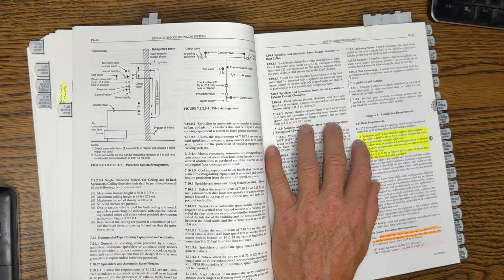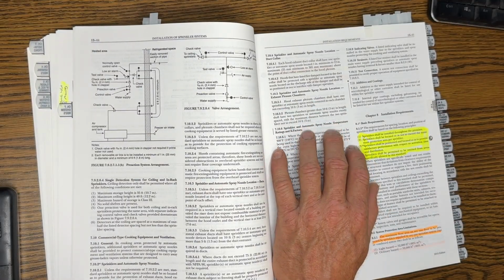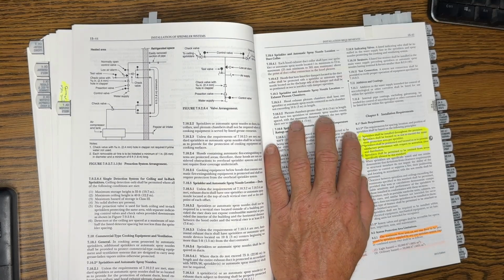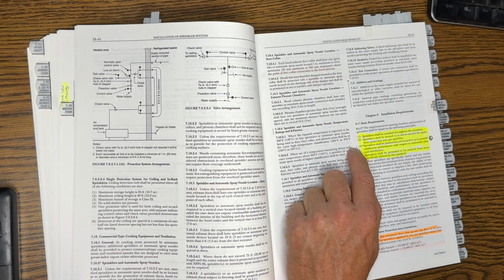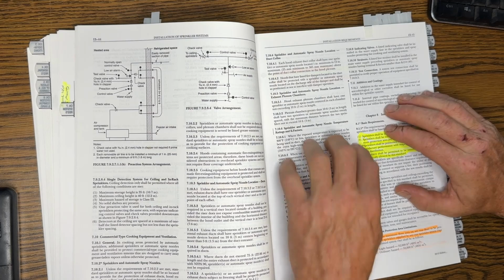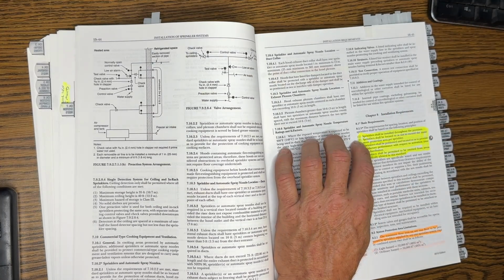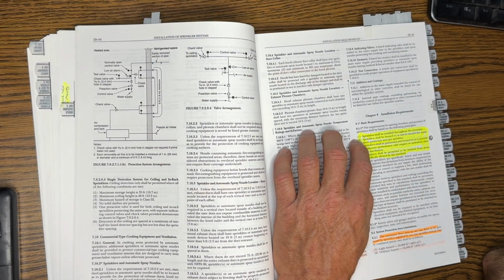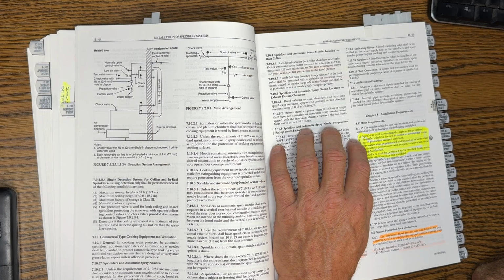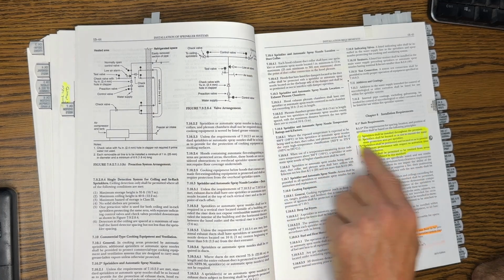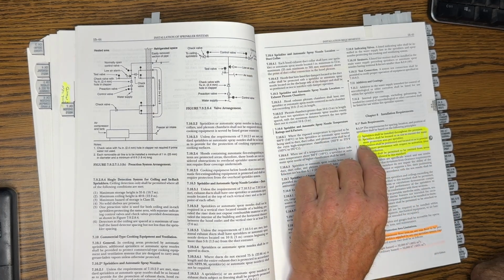Chapter 8, the question for this reference is 8.1.1: which of the following does not apply to sprinkler head installation? And you'll see it here. Sprinkler heads can be omitted from undesirable locations. That's tricky. I want to be very clear, folks, because this is a real issue. If you look at 903.3.1.1 of the 2018 IBC and IFC, it counters this. It says that you can omit them from undesirable locations.